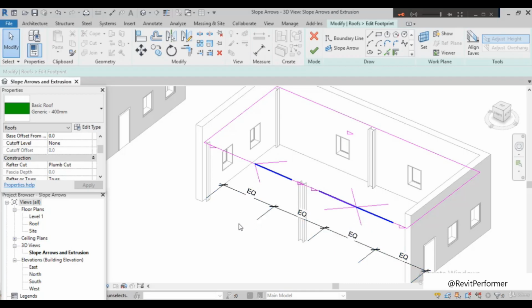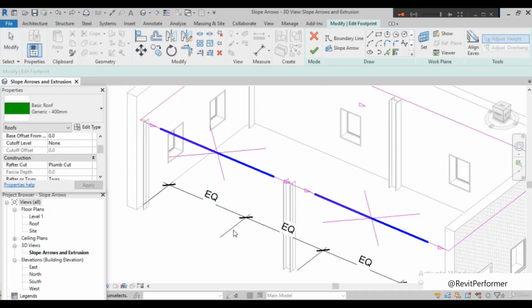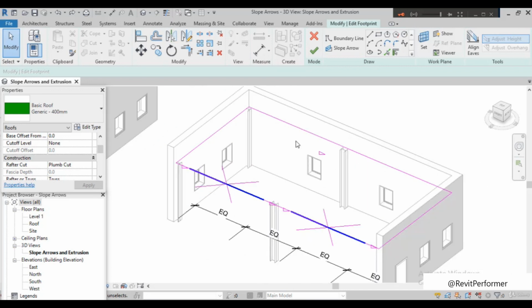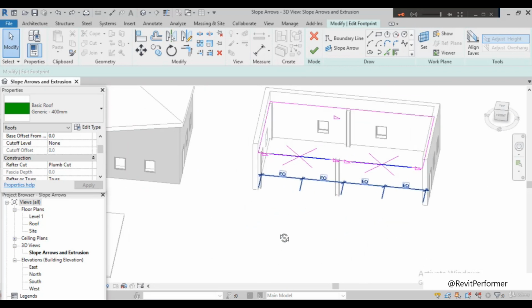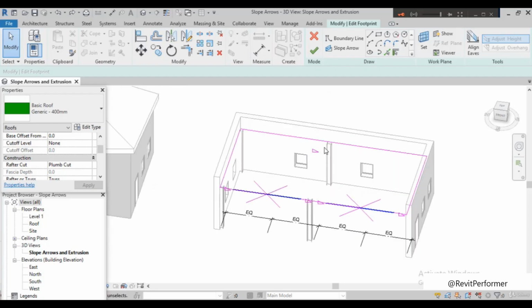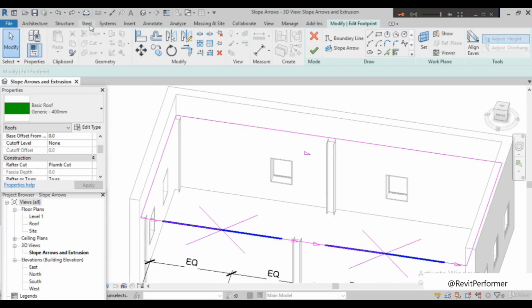Okay. Now I'm going to do Control Z first. Okay. Now here, just come to this right position, just a little bit right, orbit. And here I want to use split element, and I just want to create it in the middle of this. Okay. Now this is split element. Now you can just do that. After doing that, go to the slope arrow.